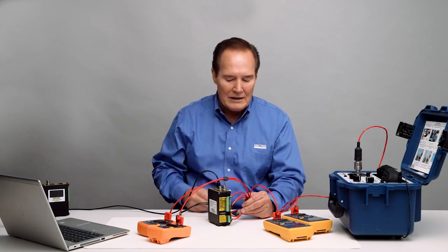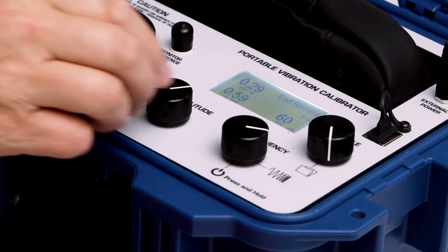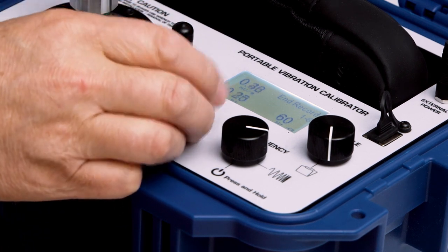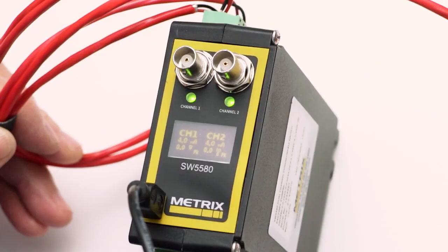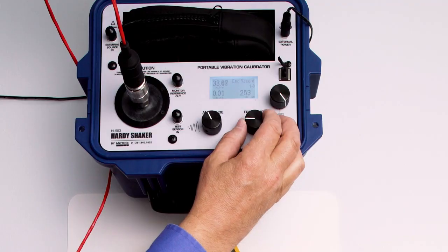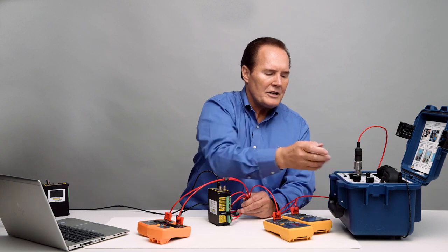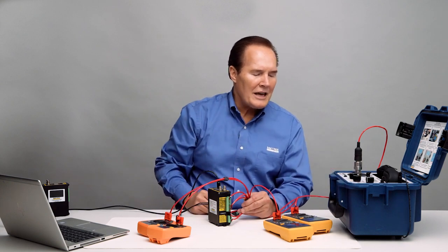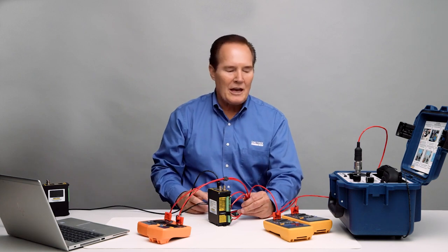There's no acceleration alarm. What we'll do now is go back down in amplitude, and then let's increase the frequency up to 200. You can see the alarm's clear because we're non-latching. We had that set. And let's go ahead and go up to 250 hertz. Nice thing about the Hardy shaker, the HI903, is the amplitude doesn't change when you change the frequency. It goes back to what you set the amplitude at.